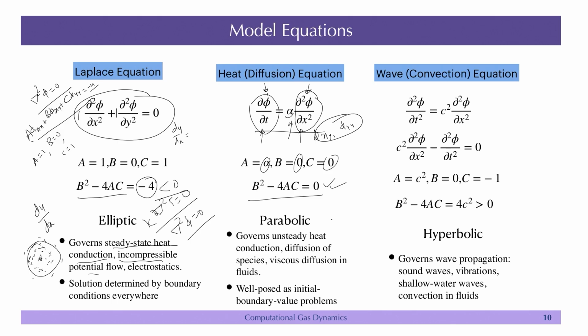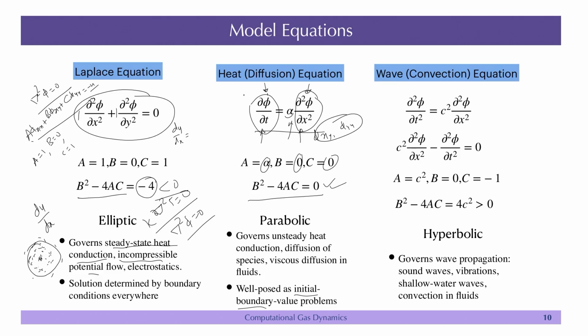We will see that if you solve the boundary layer equation, the t is basically played by the beginning of the plate. So, the t is replaced by an x there, but there also all the information is travelling at x greater than 0. It cannot go to x less than 0, just as it cannot go to t less than 0, because that is not allowed. It is a characteristic, and there is a discontinuity there. These kinds of problems are called initial boundary value problems. Initial, because you have to give something at t equal to 0, and boundary value, because you have to provide the boundary condition.